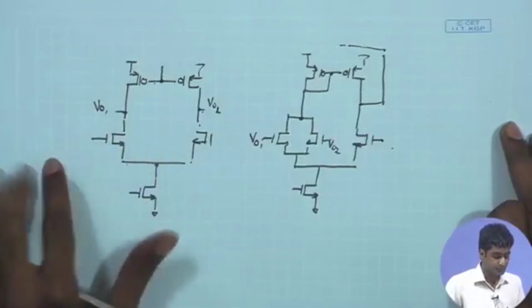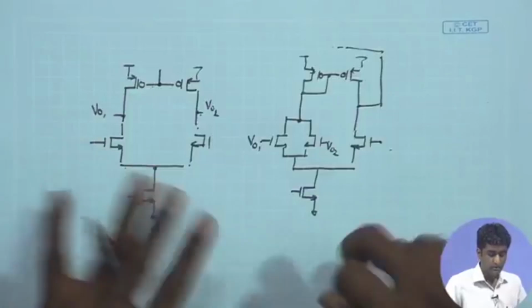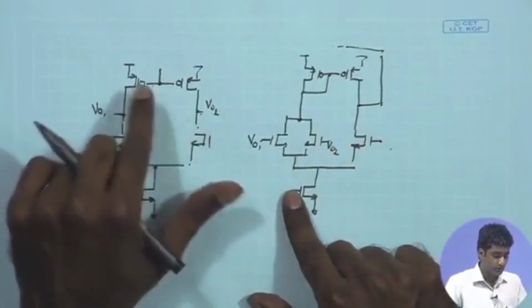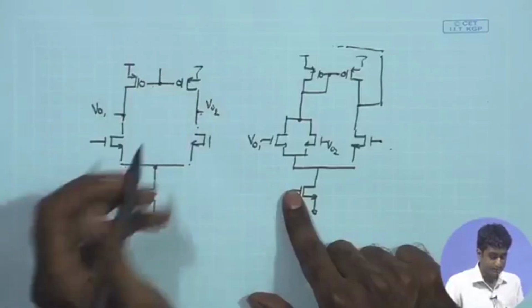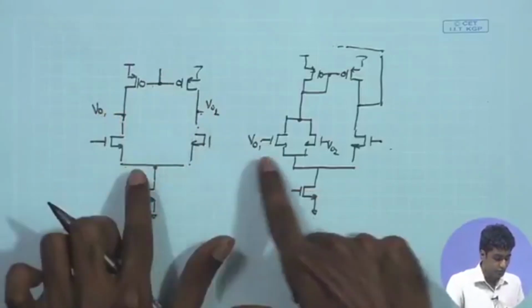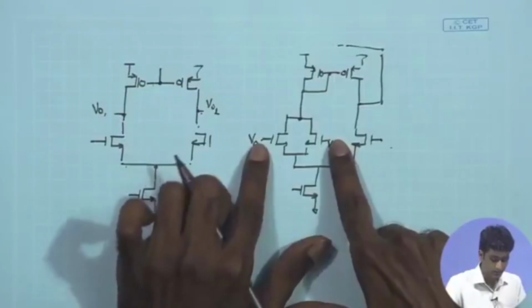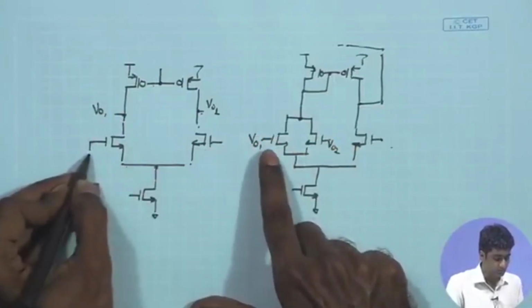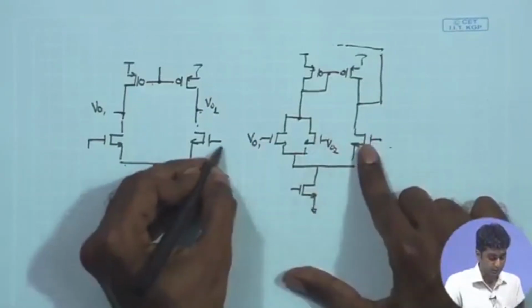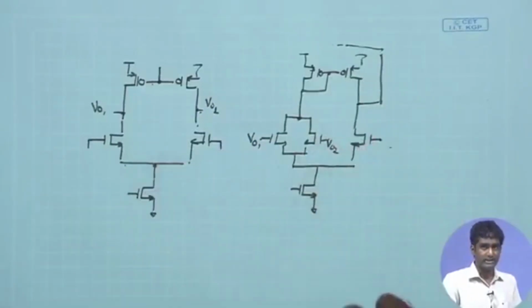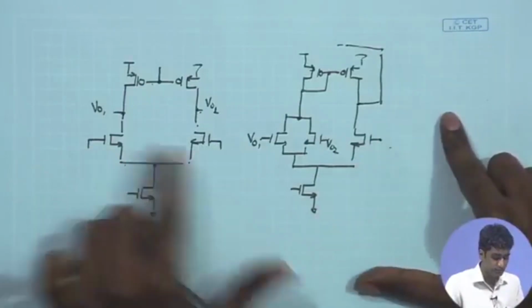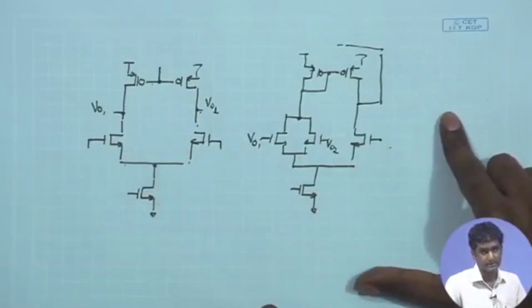And to do that, if we talk about the first case, when we are, for example, opening the loop over here, in that case, my VO1 and VO2 are still connected to the input of the error amplifier. These two are anyway set to AC ground or their respective DC bias point. So, if I talk about the exact simulation, of course, whatever DC bias point was applied at these two inputs, we can keep it as it is.